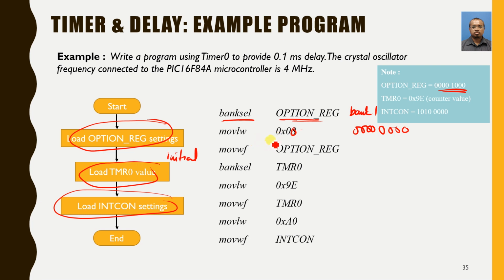Alright, so if you don't want to use prescaler, use this one, meaning you're not using prescaler, meaning it is 1 to 1. Okay, so if you use PSA equals to 1, so prescaler is don't care, meaning it doesn't really require it. Okay, because you set PSA.